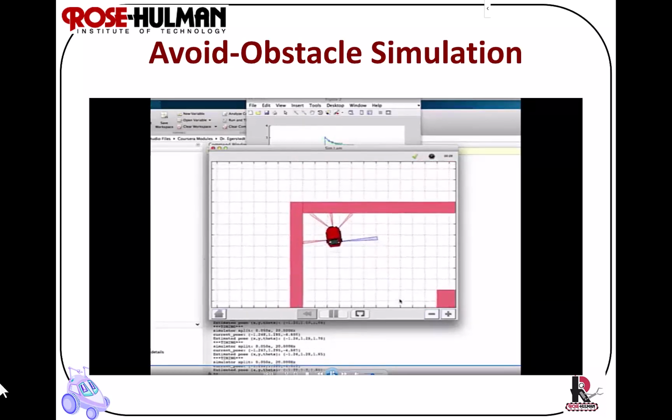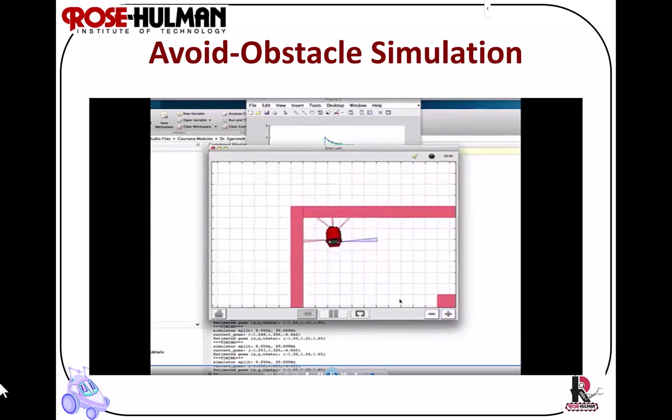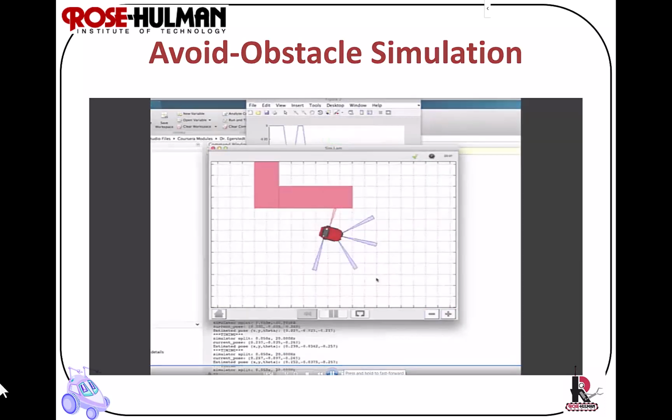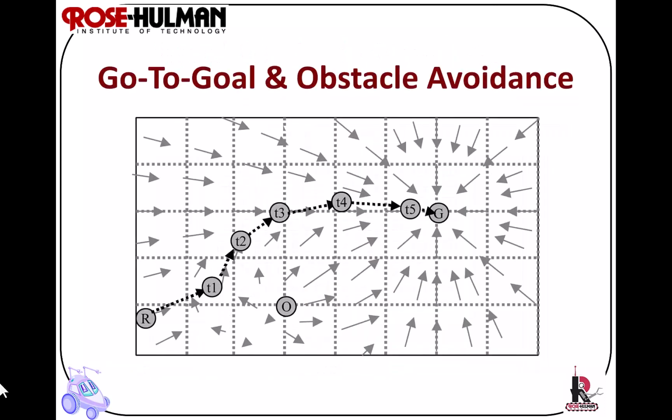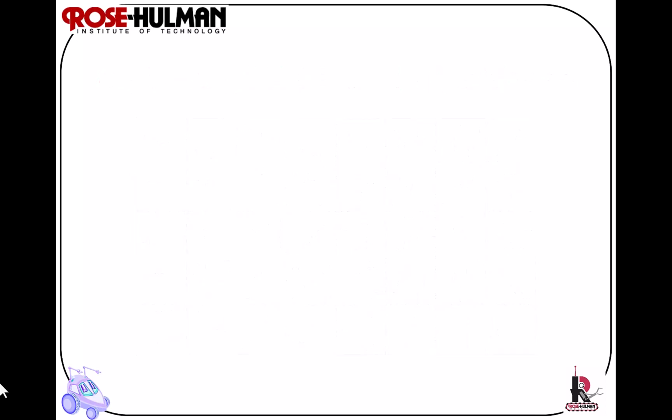And this is what your robot should be doing when it's in full state machine for either smart wander or smart follow. Once again, you're not going to do go to goal for lab 2, but you will do it for lab 3 or 4. You're going to have a world of potential fields and obstacles repelling, as well as a goal attractor force. Your robot would be moving from T1, T2 to the goal while also avoiding the obstacle as shown in this image.